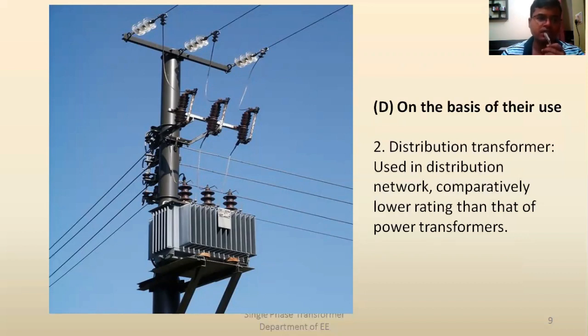Okay, now there is practically no difference between the power transformer and distribution transformer. Both transformers have same basic principles. The only difference is the relationship between maximum efficiency and the load on the transformer. Okay, power transformer is located at the generation end and hence has to transfer whole power that is generated by generating station, and hence is designed in such a way that it gives maximum efficiency at the rated or 100% load.